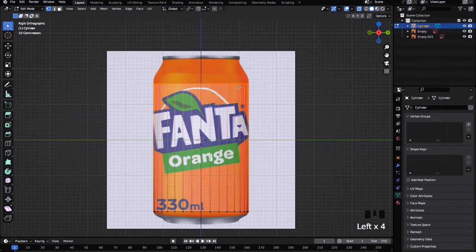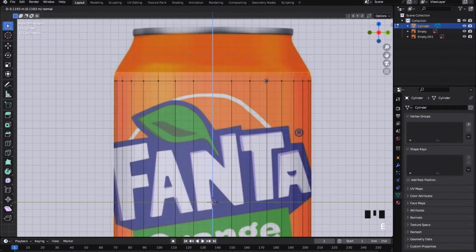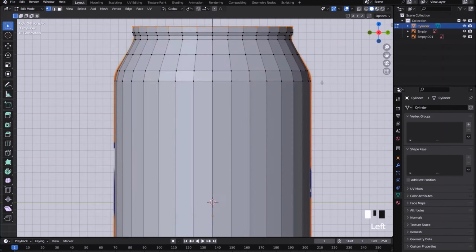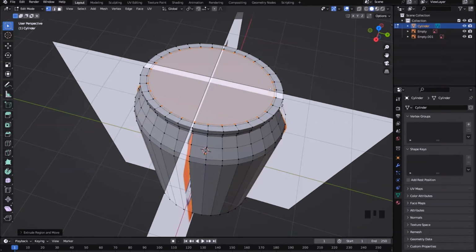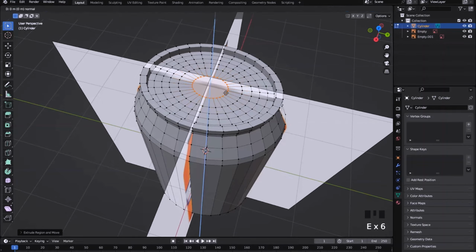Select the area you want to extrude, then press E, move the mouse up, and press S to manage the area you want to shrink to suit the image reference exactly. When you get to the top, press E to extrude and then S to shrink it. Again, hit E, then S, then drag it down with your mouse by pressing G, then Z. Following that, simply hit E and S, but on the final one, simply press 0.